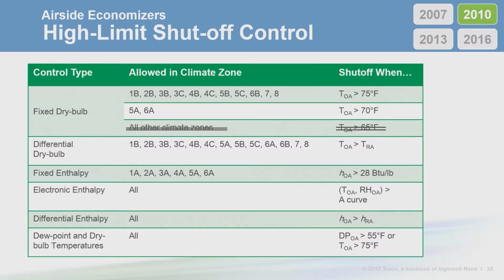In the November 2010 issue of the ASHRAE Journal, Taylor and Chang discussed concerns about sensor inaccuracy and suggested that fixed dry bulb control provides the best combination of energy savings and maintenance with the least risk of sensor error. This helped justify the reintroduction of this fixed dry bulb control in 2013.